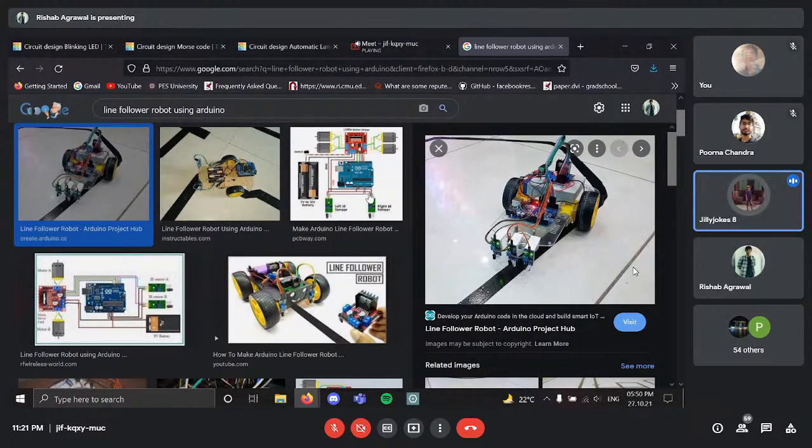Sir, the thing is, if you bend the LDR to the floor and there is no light coming from the front side, like it's completely bent down, then however the light intensity is, its resistance always stays the same. There's no external light to trigger and vary its resistance and give the output.